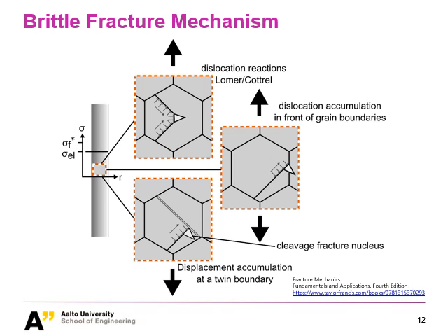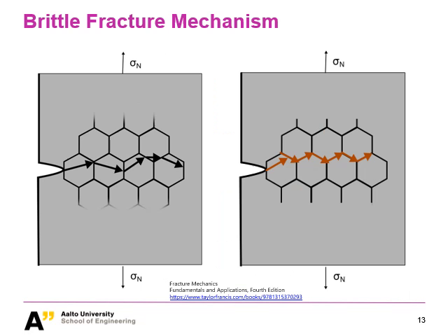After the crack initiations are developed, what we need is just to let it propagate, right? As we observed from the figure before, from the micrographs, there are two types of crack propagation mode in brittle fracture. One is intergranular, one is transgranular.